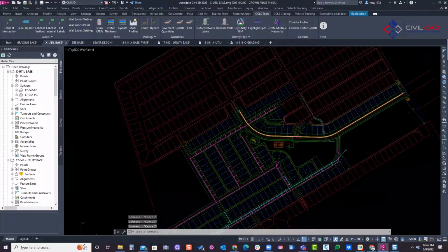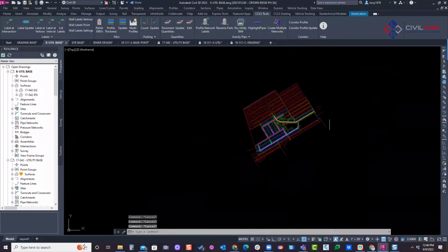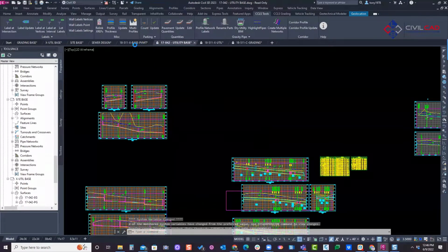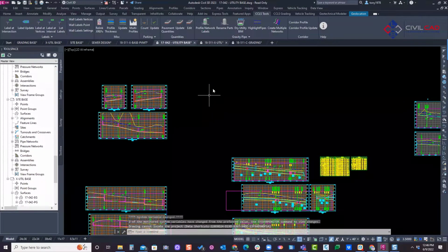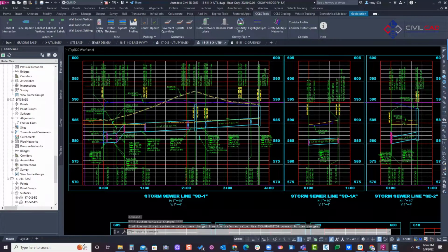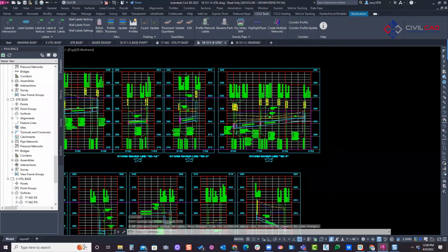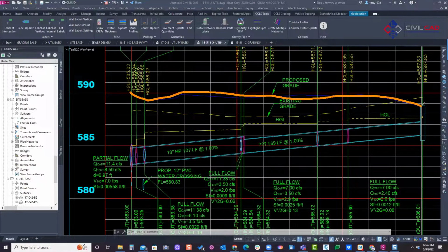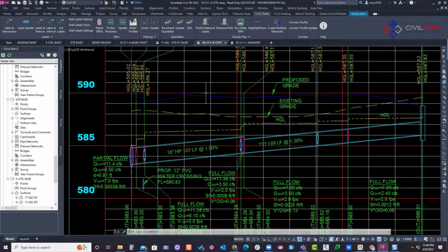Another app that we have, we'll talk about, let's see here, pull up an older project. This one. Now, I've had certain cities I've dealt with when I was doing design where they requested, can you show profile thickness on your utility profiles? Well, this is not inside of a road. This is just in a parking lot. So how do you apply profile thicknesses? So we created an app that you can adjust the thickness and different multiple layers for your profile.